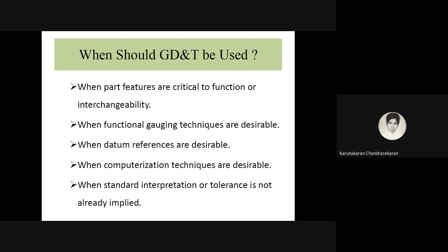The same drilled hole should accept another component with the given diametral tolerance. If it is not fitting, then there is no interchangeability. Accordingly, if you want an M10 nut, a 10 mm metric nut, and you have a 10 mm bolt, both should have fit.